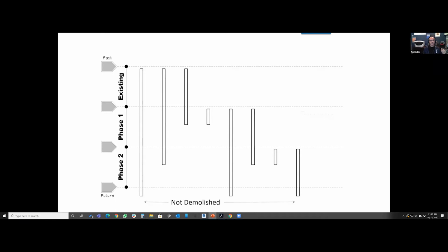All right, so the objects at the bottom here that poke all the way down, those are not demolished ever. So they're going to exist into the end of the project. So just to recap this, let's look at it from the point of view of one of the phases, because again, at the moment, it's very difficult to tell what's what, other than that I described it to you and pointed to things. Looking at it, there's no way to tell. So the different graphics that get applied to elements in a phased model are completely dependent on the view that you're viewing them from.